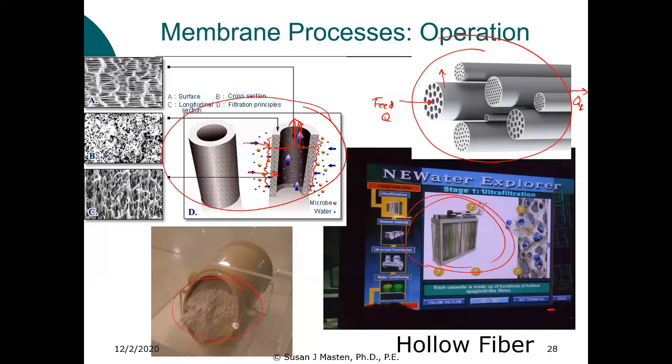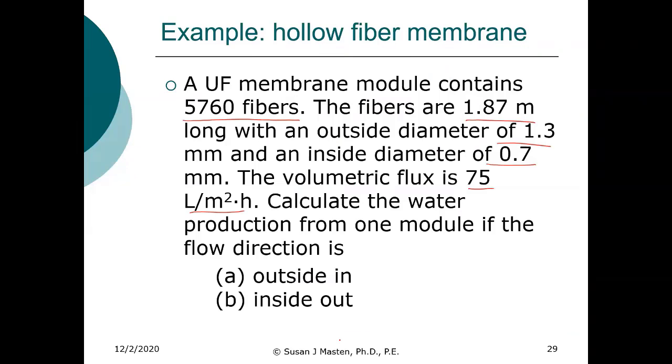When we were in the higher country and we were treating spring water, typically we then just filtered it through the ceramic filters. It was sufficient because it was both spring water and it was the high country, so there was less potential for contamination. But downstream of the donkey paddock, we needed to make sure that we didn't clog the filters because of the turbidity, removed as much of the bacteria and viruses that we could on the ceramic filters, and then also treated with chlorination to ensure that we killed everything else. And we made sure that when we chlorinated, we let that water stand for the requisite 3 hours to try and make sure that we got the CT needed to disinfect. And like I said, nobody got sick. So that was a good thing.